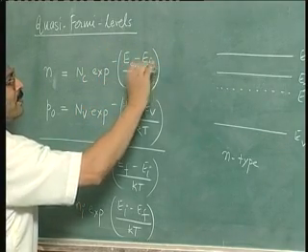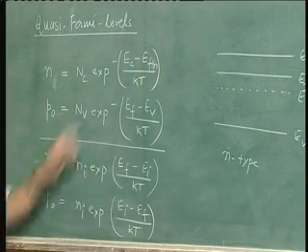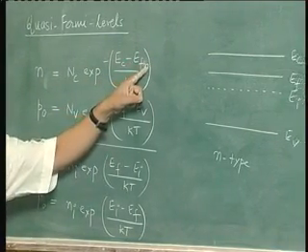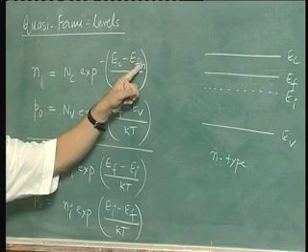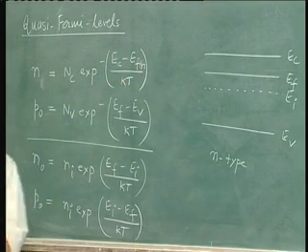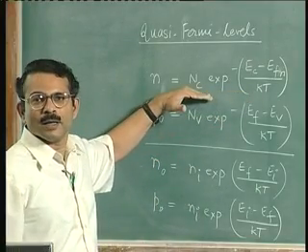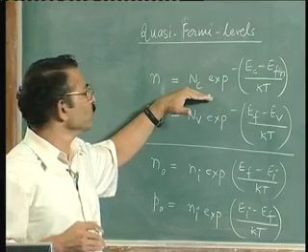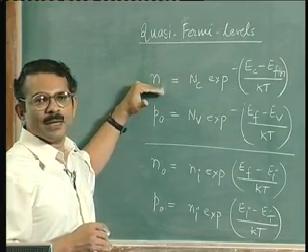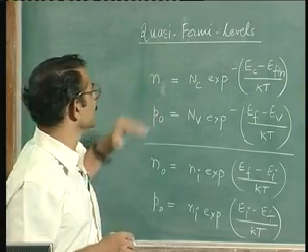So the Ef will have to therefore change to a new value that is called Efn. This is called the quasi-Fermi level for electrons. So it is that Fermi level which, when you substitute in this formula, which is similar to that under equilibrium, you will get the concentration of the electrons, and similarly we can get the concentration of holes also, as we will see.